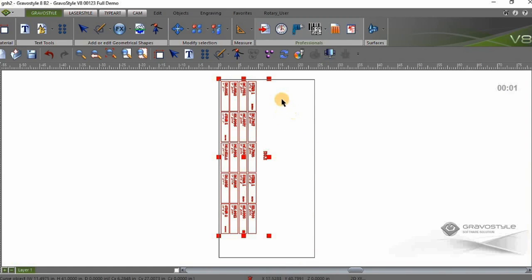Right now this is all one piece, and you see I've positioned it kind of in the upper left corner here, which would coincide with the origin of the engraving table on the IS8000. We can leave a little bit of margin in here for cutting, so our spindle and nose cone is not right against the stops, so we've got a little bit of a gap there.